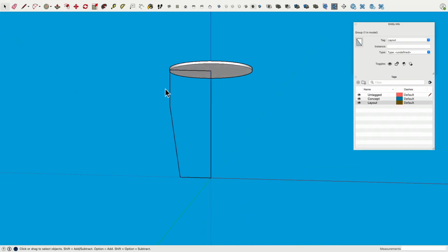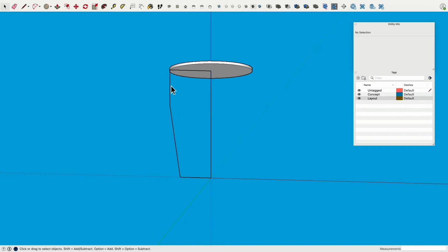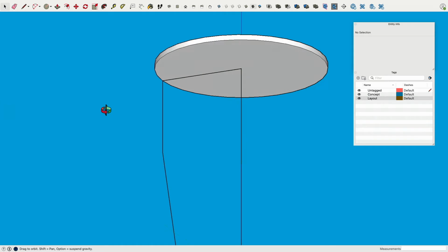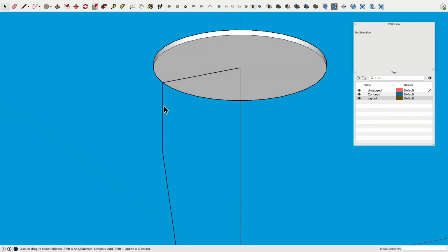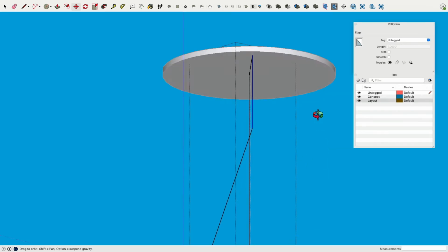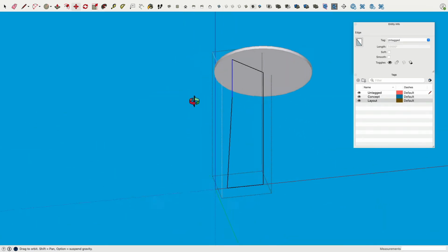This line, this left one, is half an inch too far to the left. I will show you now how we can move this back. Maybe to this view. Double click. This is important because then we added the group. Now I can select this line, move command, and along the x-axis, you see how there's this red dashed line. If you see a black line, you're going to totally distort the piece. You see, this is not planar anymore.